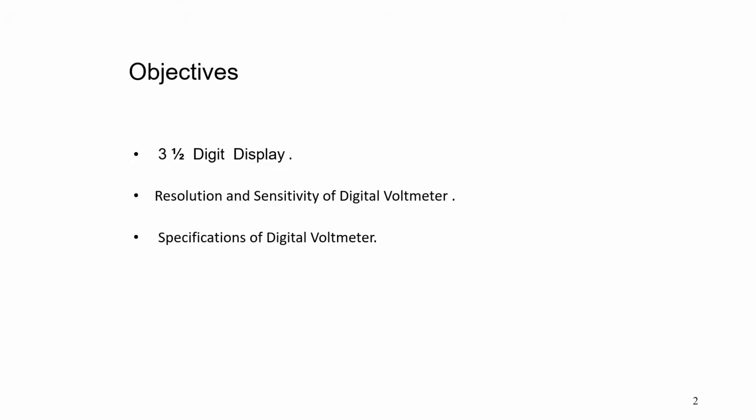This time period is measured with an electronic time interval counter, and the count is displayed as the number of digits on a tube or a display. Basically, the ramp type DVM consists of a linear ramp which is positive going or negative going. The range of the ramp may be plus or minus 12 volts, while the base range is plus or minus 10 volts. In this case, a negative ramp has been selected.